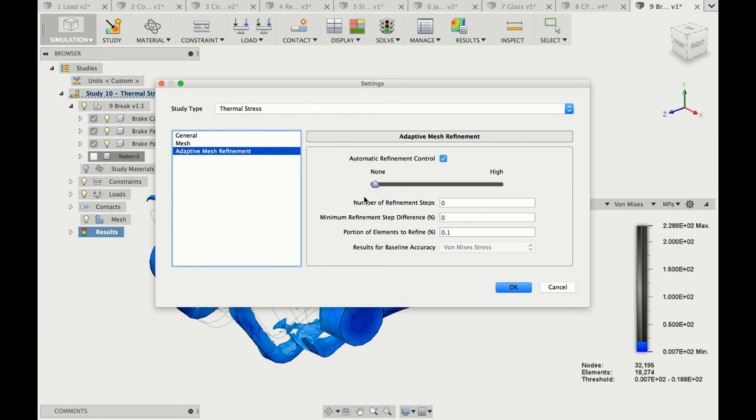So without asking a question, it gives you the solution. The cost is that the resolution is lower. However, engineers typically don't have the knowledge to do the simplification to fix the mesh issue. So the voxel mesh is kind of our plan B. When things go wrong, engineers still get their results.